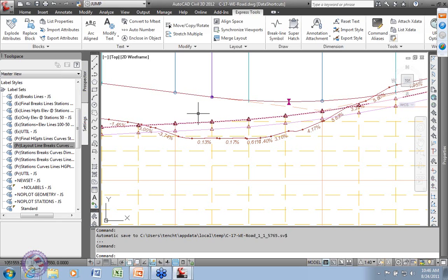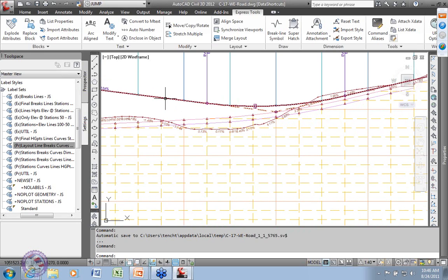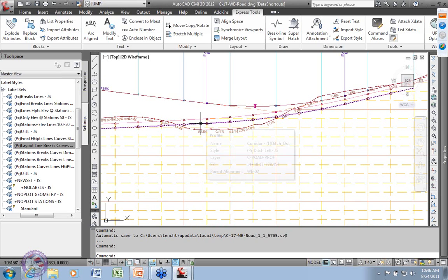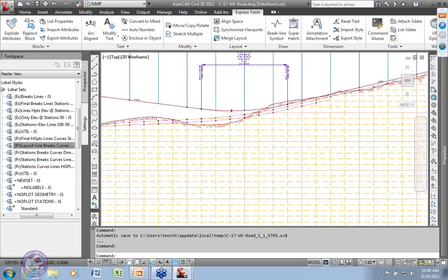And notice that obviously my design profile has changed up here. My ditch, which at some point was connected to it, came from the current condition of my corridor, and I created that profile from my corridor, and my ditch are no longer in sync with its current condition.